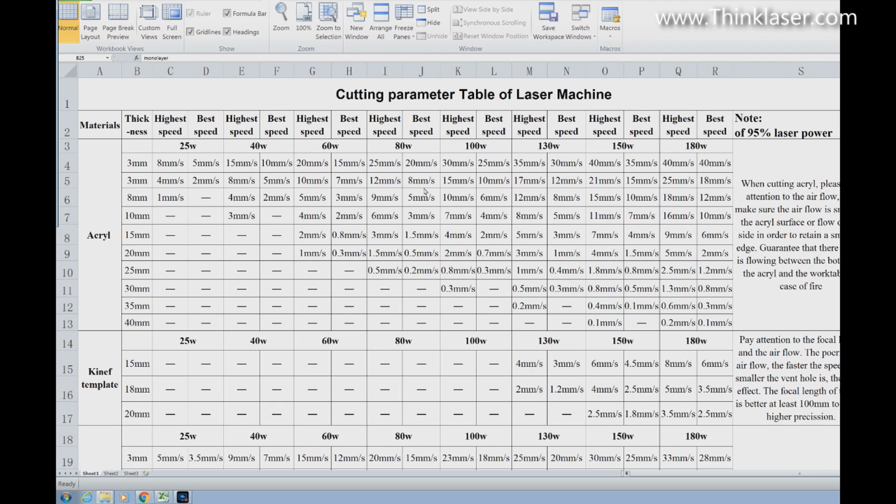So there's a sort of logic when you understand how to cut acrylic, but as a novice, it wouldn't make any sense at all. The machine is supplied with 3 lenses, a 2-inch, a 2.5 and a 4-inch lens. I've added to that collection with a 1.5-inch lens of my own manufacture. What do these figures apply to? Because they don't apply equally to every lens, because the density of the power of each lens and its ability to cut changes. So there's one major piece of information missing from this table, and that's the lens that they used to produce this data.